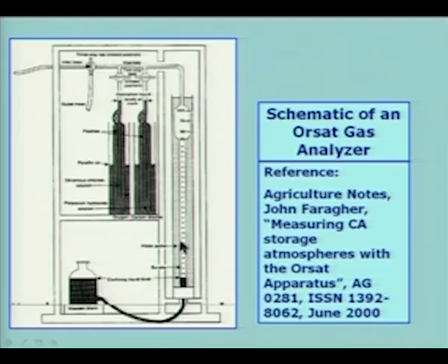volume. So, in this case I have taken a case of Orsat analyzer with just two of them, one for carbon dioxide, one for oxygen. So, this will give you an idea about how much is the carbon dioxide percentage by volume and how much is the percentage of oxygen by volume, all at a constant temperature, because this entire thing is going to be surrounded by a water jacket at a constant temperature. So, at constant temperature, the percentage by volume will also be the molar percentage, as we already know. So, it is a very simple instrument, and let us look at what are the possibilities.